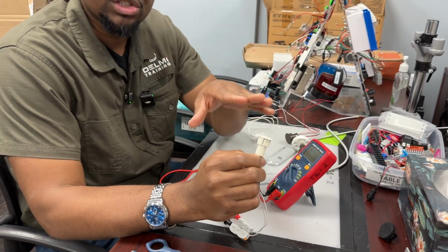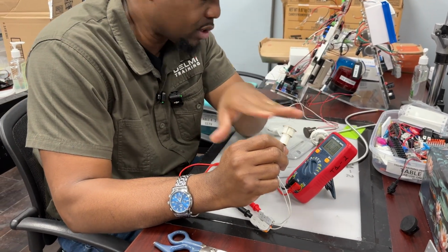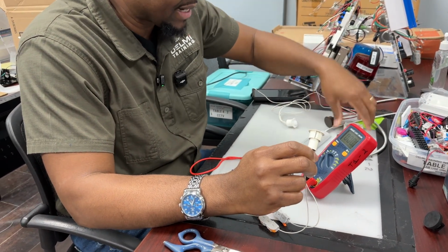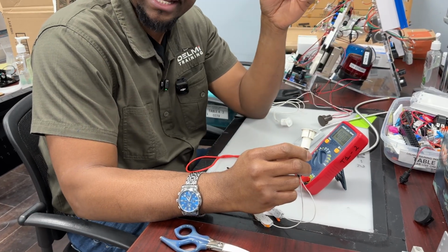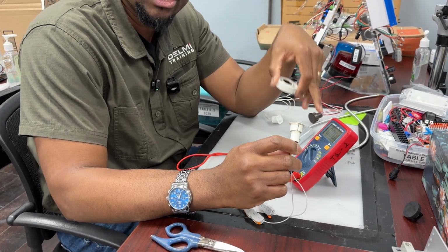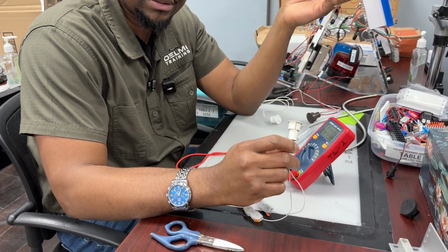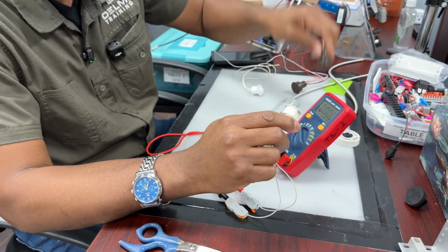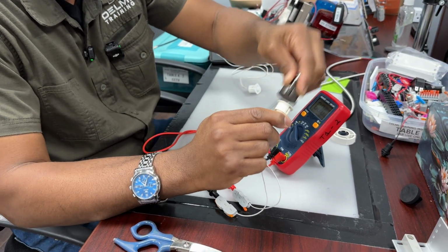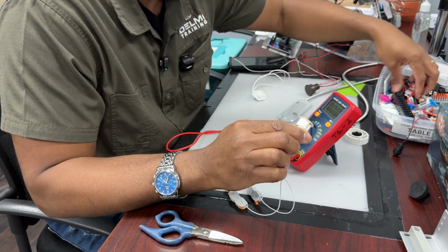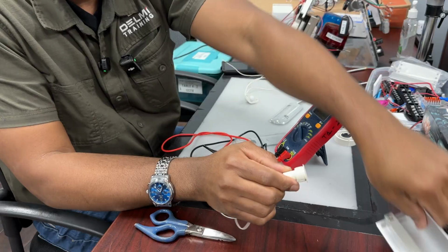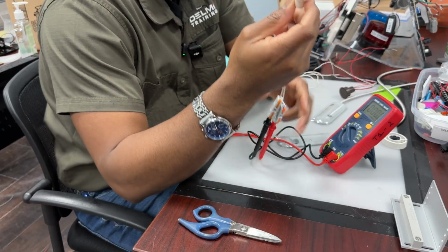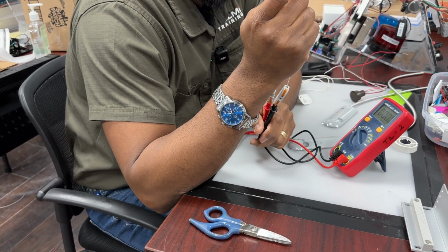So let's see. If I want to change this state, and this is not faulty, I just need to grab a piece of magnet. It could be either that magnet or this magnet, and I'm going to bring it close by. When I bring it close by, I'm expecting the noise to stop, the circuit to be open. So let's take a look. See, I brought this close by, it's still beeping. Nothing is changing. It doesn't matter what magnets I bring. So right away you can tell that this is a defective contact.